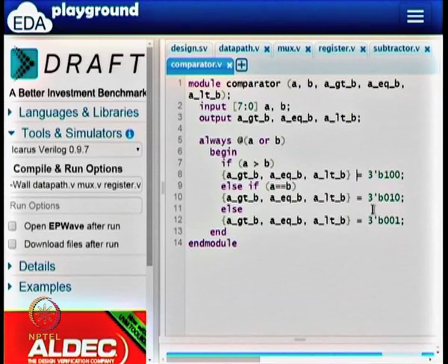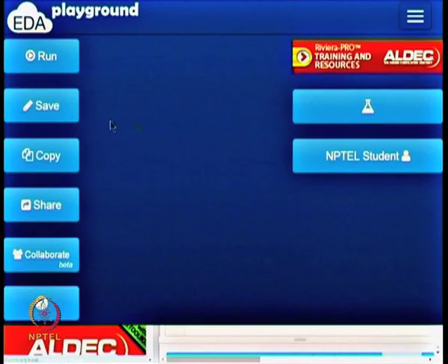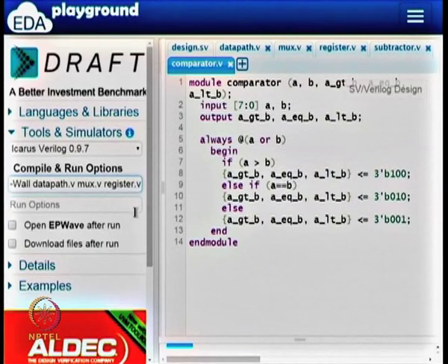And so I am going to use the less than symbol here, so I am going to use this statement which is a signal assignment statement. I will talk about this later, and we are done. So this takes care of the comparator also. If A or B changes, then this always block is evaluated and you will get one of these output bits to be a 1. So let me again save this, and I am going to add comparator also as a file.